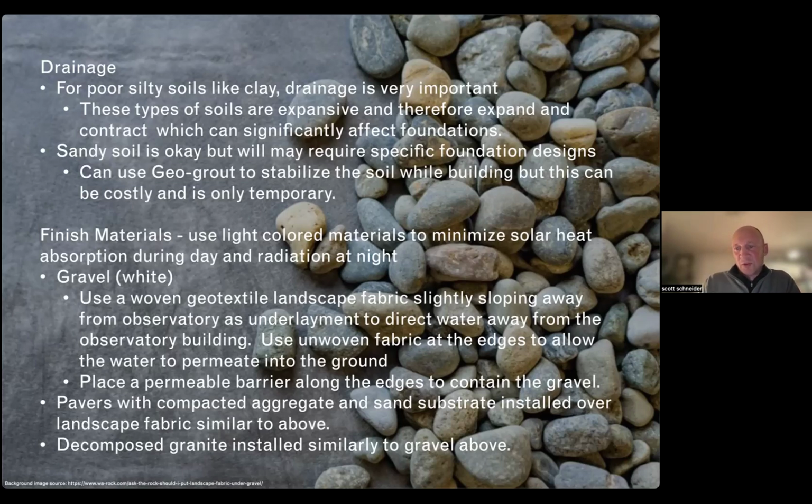Then when we start getting into the topsoil and finishes, it's a good idea, if you have mainly posts or piers for your foundation and the underside of your building is exposed, to put gravel underneath.